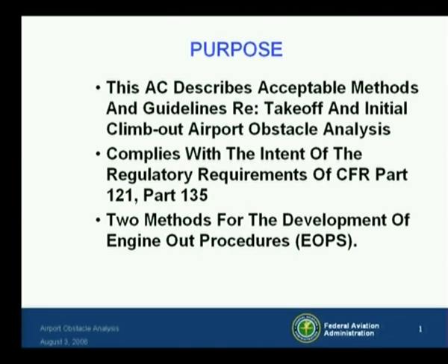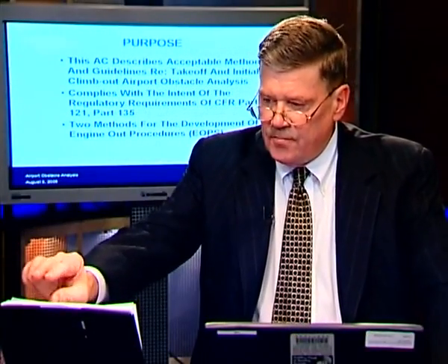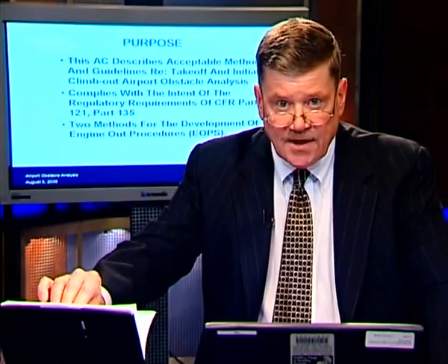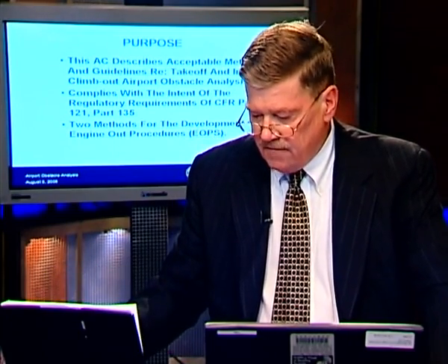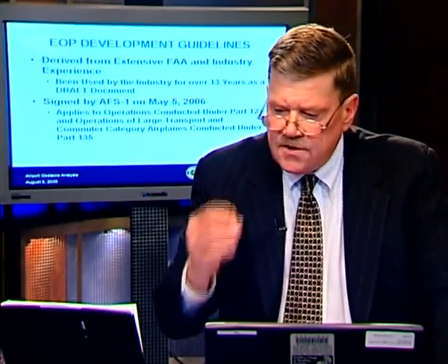It complies with the intent of the regulatory requirements of CFR Part 121, Part 135, and other associated one-engine inoperative, or OEI, airplane performance requirements relating to turbine engine-powered airplanes, and it prescribes two methods for the development of engine-out procedures, EOPs. This AC is really the only game in town that the airlines have been using for many years, and we're going to explain that in the future. But it does provide some very useful guidelines.